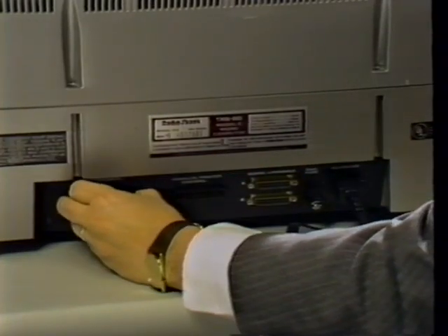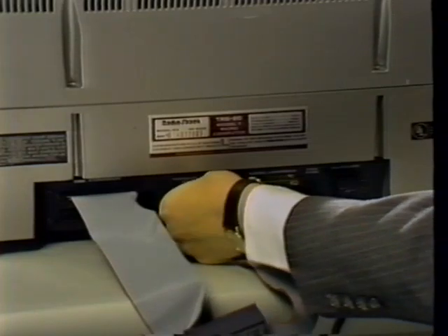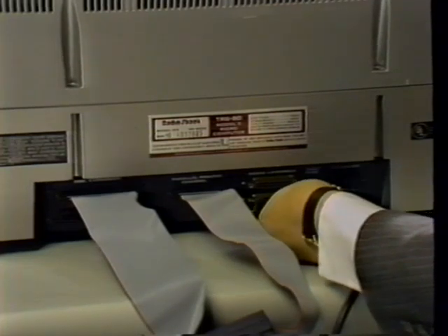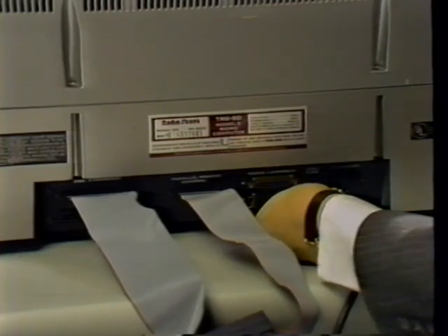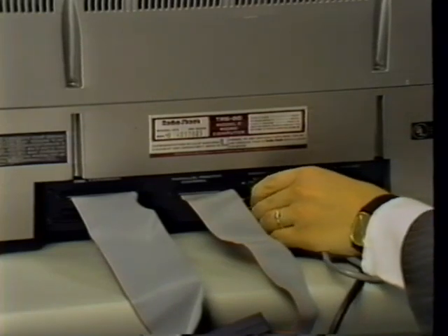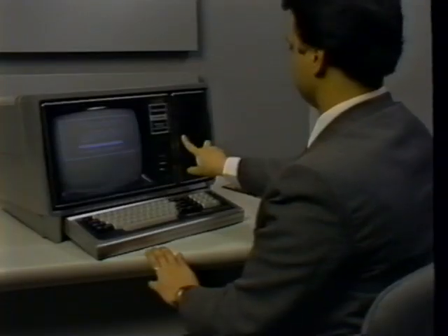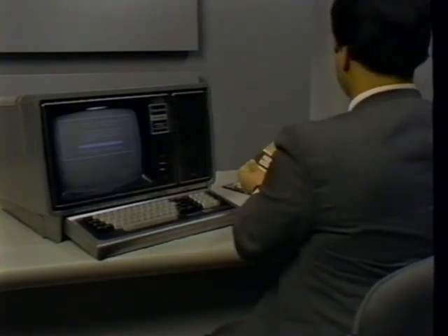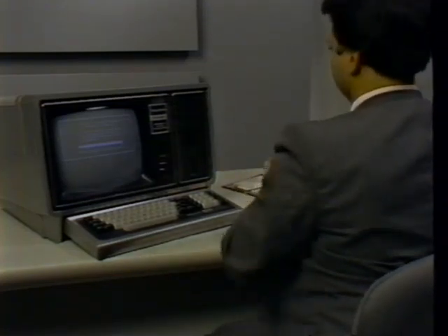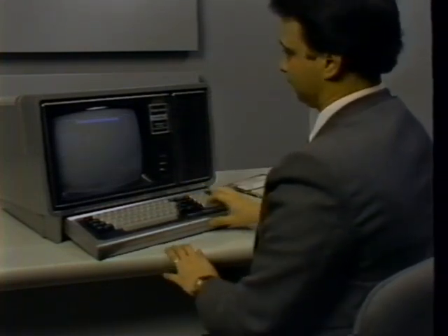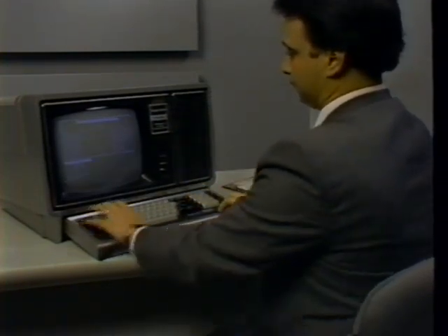The information in this section is intended to stress the importance of using diagnostics properly, as well as some limitations of these diagnostic programs. It is to your advantage to test a unit in every possible way before releasing it to the customer. This means that you must run all diagnostics for more than 1 or 2 passes. Intermittent problems, which are the cause of most customer dissatisfaction, will often not show up on the first test. Be sure to duplicate the function that the customer attempted before assuming that the problem is fixed.